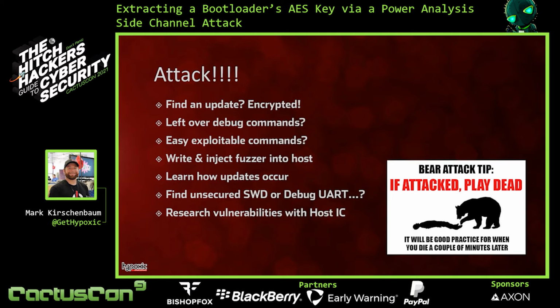Moving on, a lot of times nowadays we'll write fuzzers, which basically just try a whole bunch of different combinations and see if we can make this crash. And if we make it crash, then we know that we've hit something that we weren't supposed to hit, and we iterate through that and try to find a method of extracting the firmware out of these devices.